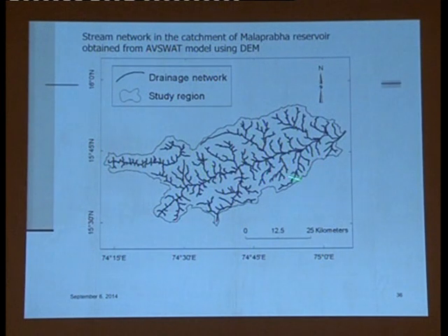So we try to calibrate the hydrologic model that I have showed you, and based on that, we try to estimate or parameterize this model configuration in such a way that the runoff that we are obtaining here is comparable to what is actually observed. And once that is done, then we say that our SWAT model is now ready for implementation for the future climate scenarios. So these are the collection, as I said, some PowerPoints, and based on that, we try to look at the sub-basin outlets, etc.